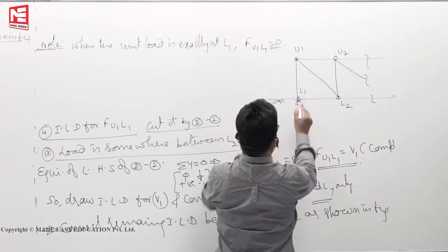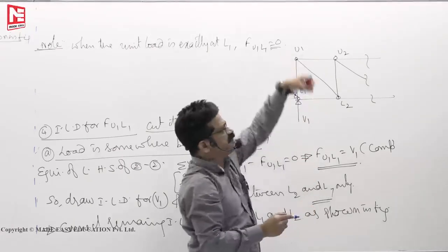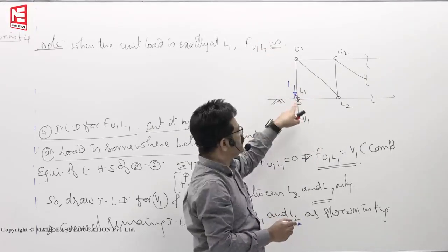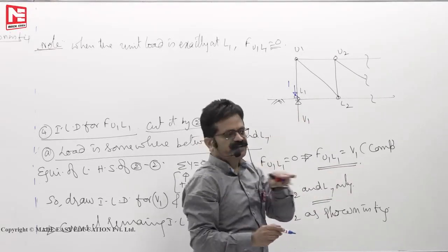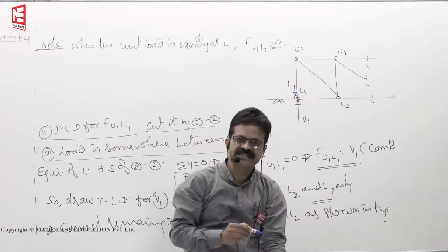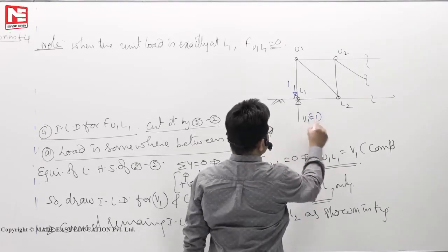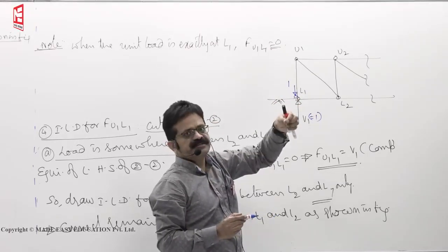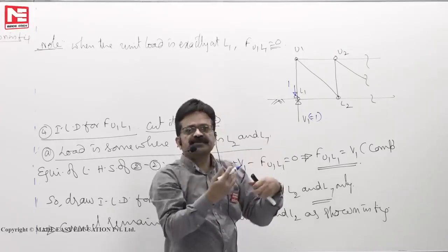So suppose unit load 1 is there, resting on the rail, the rail is resting on the cross girder, and the cross girder is resting on the support, because at the first entrance point there is a cross girder. So it directly transfers to the support. So V1 becomes 1. Then the member above the cross girder will not take any load, because the cross girder is resting on the support. Directly the support will take it.